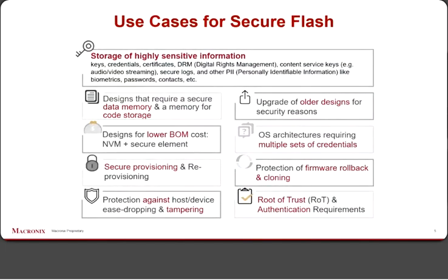So I've already mentioned some of the use cases for secure flash, but I want to mention a few others. One of them is an opportunity to lower the BOM cost. Today, you look at designs that frequently have these secure elements. These secure elements are essentially devices that help with the provisioning. They store keys. They also are involved in secure boot implementation. And so if you can have the memory device do that, well, you're going to be able to lower your BOM costs and have fewer devices in your design.